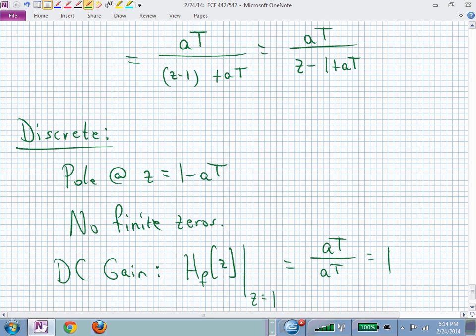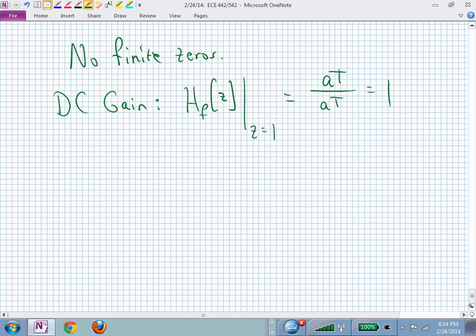And now you have a way of finding difference equations instead of solving differential equations. Or instead of filtering with Rs, Ls and Cs or op amps in the lab, now you can find that equivalent in your computer and numerically create that filtered input waveform with a 12th order filter if you want.